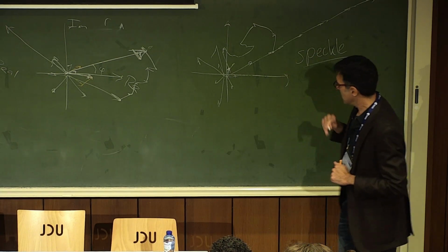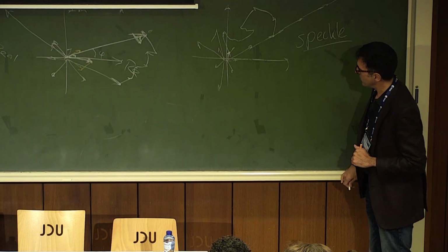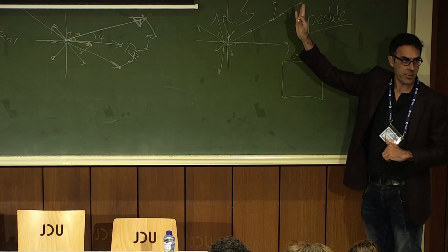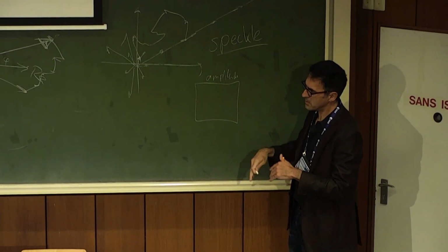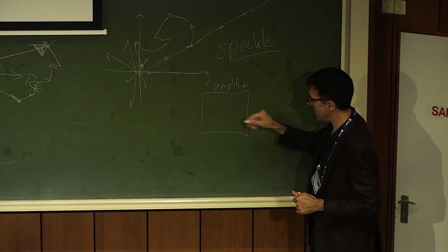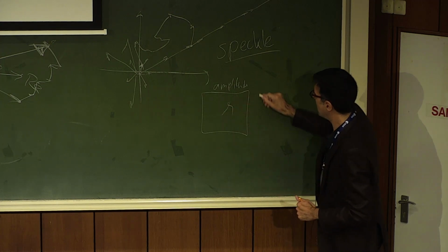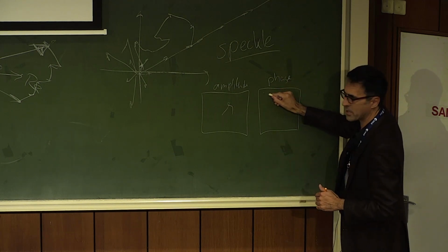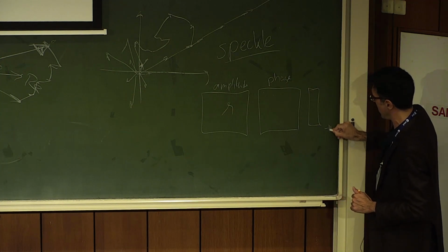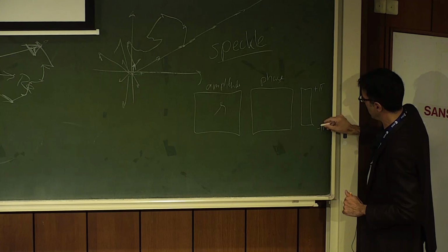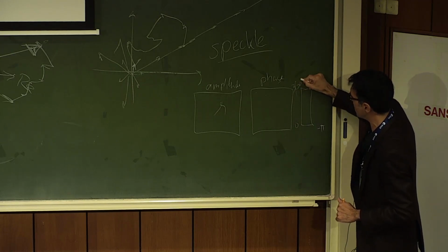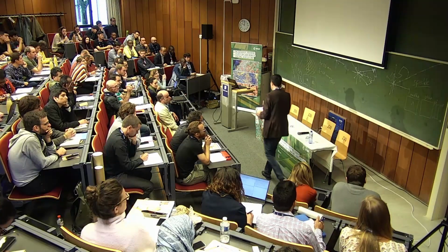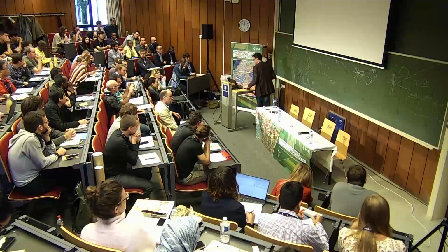So if we now make an image, and I hope that Magdalena is able to show you this in the afternoon, if you look at the radar image, we simply look at the amplitude here. We will recognize things. I showed you several amplitude images before the break, with San Francisco and the mountains in China, whatever. So this is recognizable. If I look at the phase of that same SAR image, every pixel will be different. If I put a color bar next to it, it would vary between -pi and +pi, or between, let's say, 0 and 360 degrees, whatever these angles are. But it will be a completely messy picture. I will not be able to distinguish it. Now, this is also the trick for interferometry in the end.